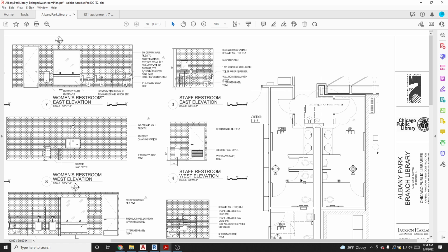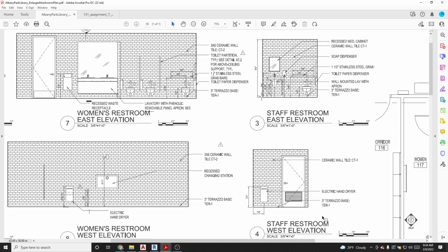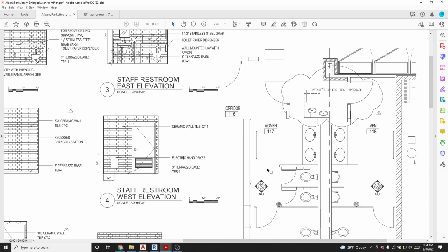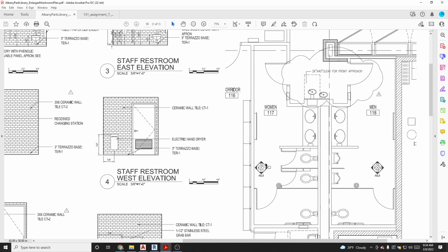So again, these arrowheads here describe which directions we're going to take a look at for elevations. So these act like cameras, and you're standing in their target here, and you're looking in this direction. And drawing number 12 describes what happens in this direction here. Drawing number 7 describes what happens here to the right, because it's pointing in that direction. So you typically create what's happening along these walls here. So we'll do that one because that's the most complicated one.